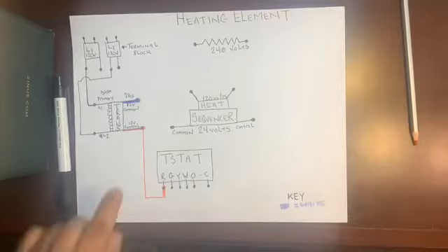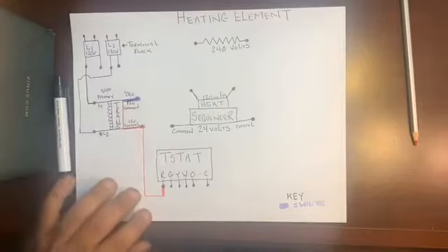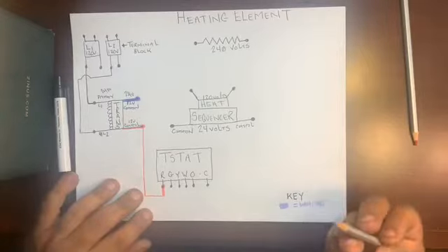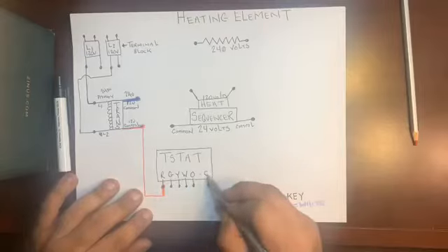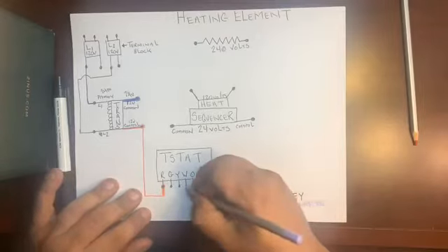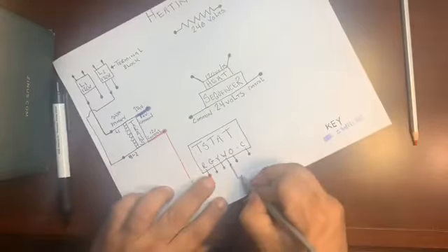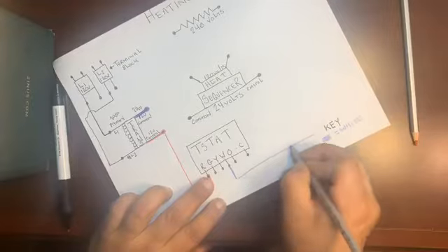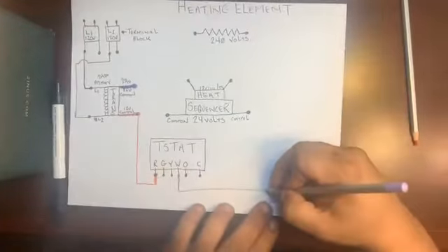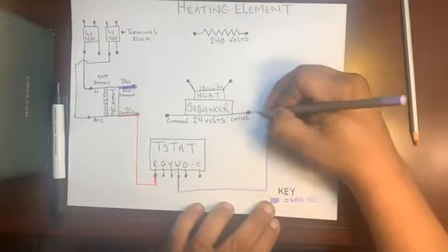So let's go ahead and complete our control side, because we already know where the common is going. Let's go to our control. We agreed that white is going to be purple. Here's our white, not our green, not our yellow, not our orange, not the common, but the white. We're going to drop down with our purple wire, which is white. We're going to bring it all the way over. Then bring it up to the control side of the heat sequencer.